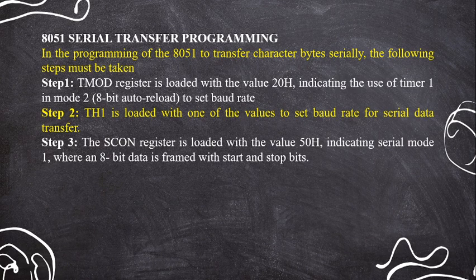And next, the receive enable should also be made equal to 1. Though it is transmission, you can write either 40H or 50H. Most important here is the mode, that is 0, 1 should be set in the SM0 and SM1 bits. Again, this value of 50H would be fixed in the SCON register.